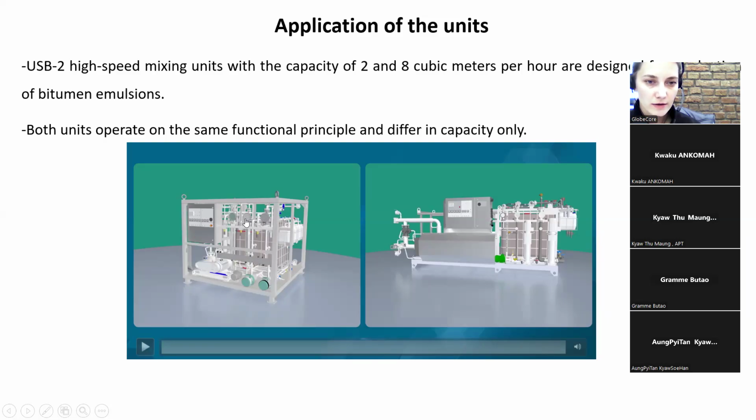These are the flow meters, and regulating valves are installed on each line, so we can dose the amount of our product that are getting inside of the tank for premixing. Okay, so this pump supplies a water phase to the blender. And this is the pump to supply liquefier to our product tank. And the same story from the right side. Both machines are equipped with the control panel.